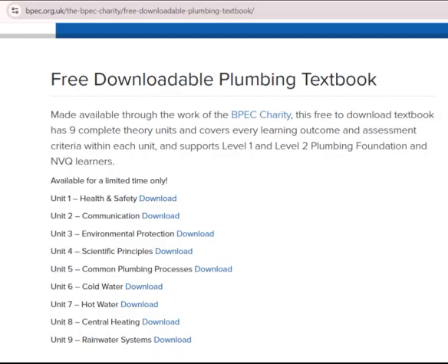Celsius, °C: this scale, using increments of 1 degree, is the most widely used by the building services industry. It has a 0.0 °C, which corresponds to the temperature at which water will freeze. Kelvin, K: this has the same increments as the Celsius scale. This means that if the temperature rises or falls by 1 °C, then the temperature also rises or falls by 1 K. However, the Kelvin scale has a minimum temperature that corresponds to the point at which all molecular motion stops. 0 K is known as absolute zero, and is equal to -273 °C. Therefore, -273 °C equals 0 K, or temperature in K equals temperature in °C plus 273.